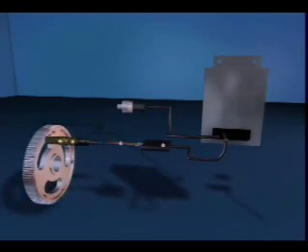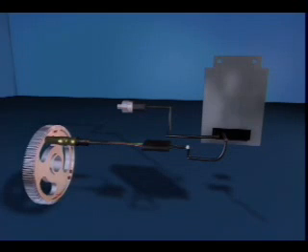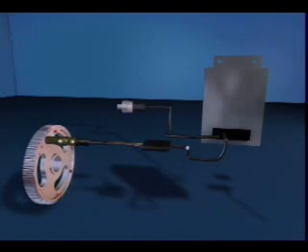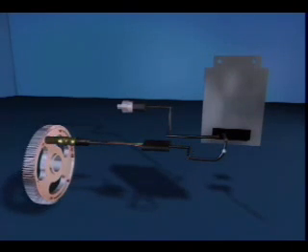Six of the 7 cast protrusions on the cam gear are located 47 crankshaft angle degrees before top dead center, 1 protrusion for each of the 6 cylinders. The engine position sensor sends a signal to the ECM based on these protrusions passing the end of the sensor. The ECM determines proper ignition timing and engine speed based on these signals.